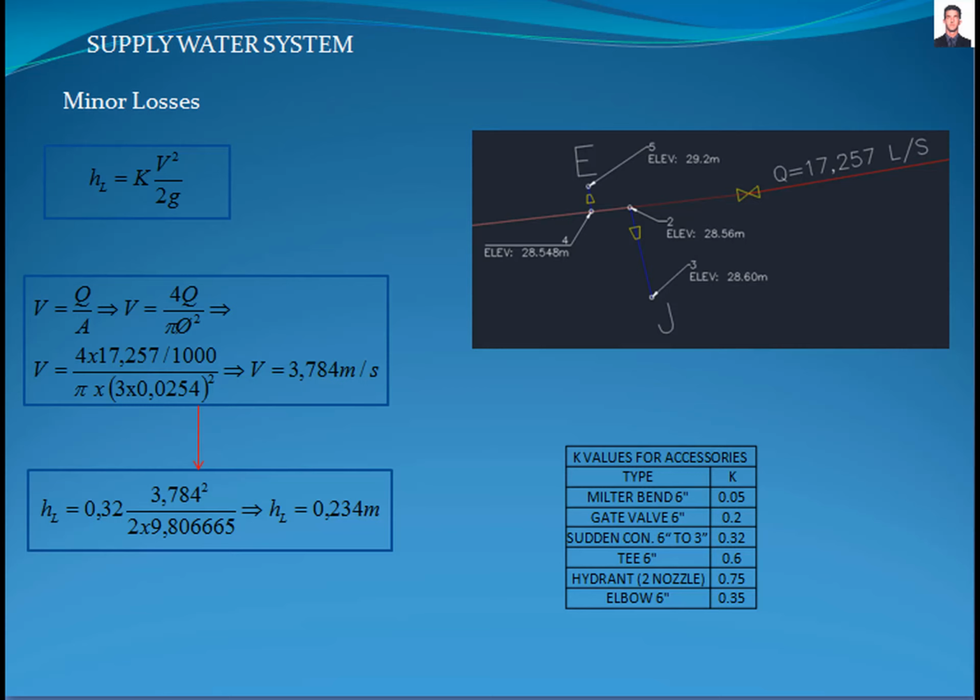With the diameter of the system calculated, we proceed to calculate the minor losses due to the connections, as elbows, tees, or valves, and create a more detailed analysis of the distribution system by dividing the network in the smallest section. These minor losses are calculated with equation 3-15 of the American Water Works Association M11 standard, where K is the resistance coefficient obtained from the figure 3-5 of the American Water Works Association M11 standard. V is the mean velocity in the accessory, calculated with equation 3-5, and g is the force of gravity.